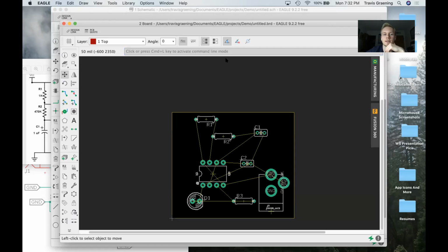One second, we've got a chat. Oh, sure. The dimension part again. If it's dimensions, then you simply click with the move icon onto the side and then drag back and forth, preferably in the middle so it doesn't go diagonal like that. Yeah, just like that. And this will probably not be the final dimensions of our board. I've just done something pretty preliminary. We can always adjust near the end, but we want a space that is big enough to hold all of our components that we're going to make our polygon over.